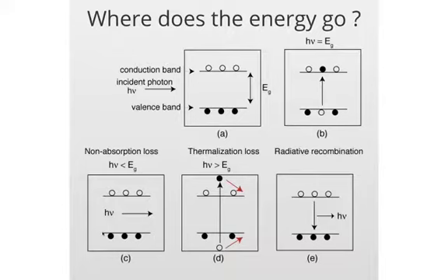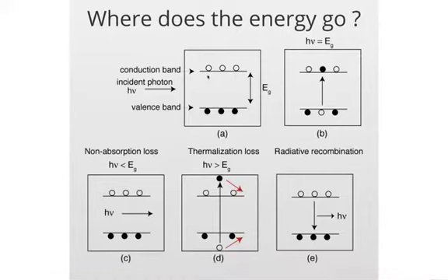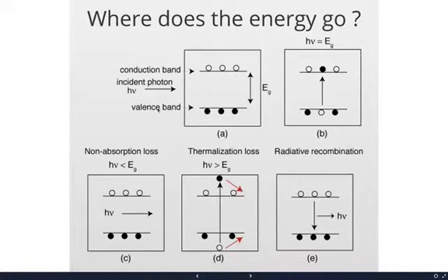But from a cartoon perspective, a solar cell can be thought of as a PN junction, which has a band gap. So a semiconductor has something called a valence band, which is filled with electrons. And at a higher energy level, which is shown here, it has a conduction band. This is the bottom of the conduction band, which is filled with absence of electrons, which is also called a hole. So it's represented by these clear circles.